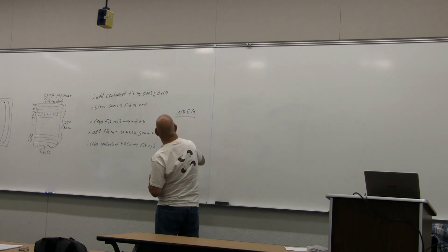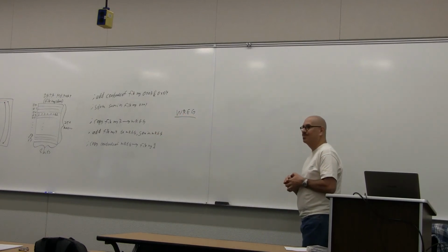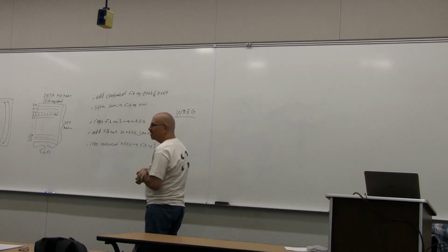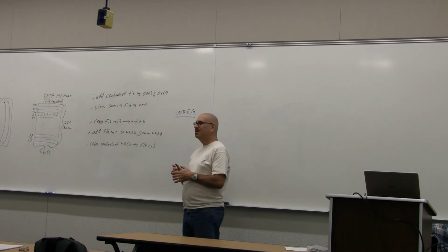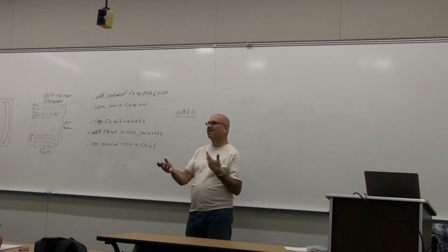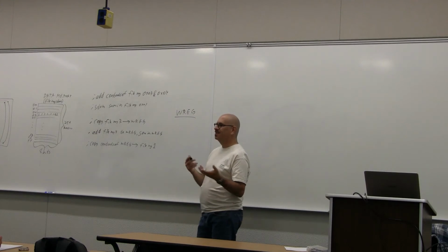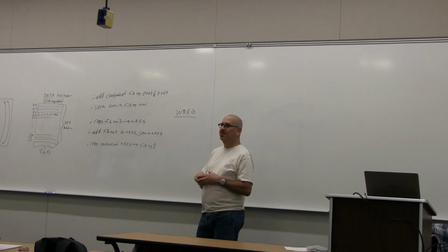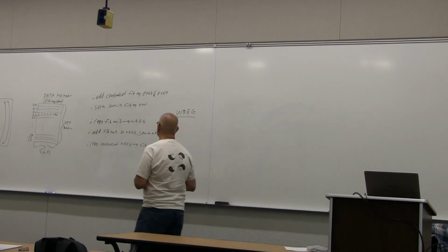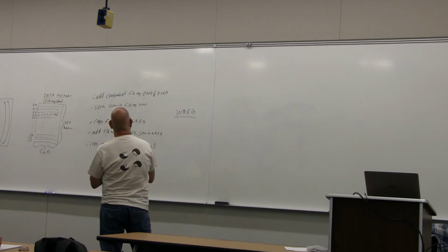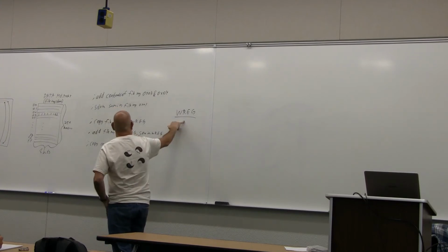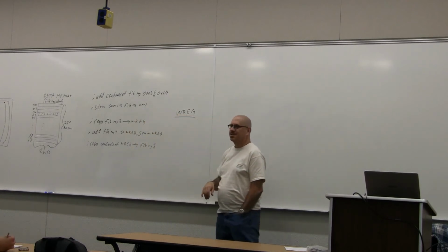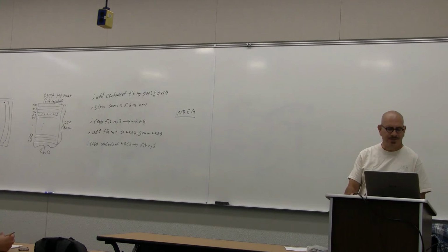All right, so the working register, WREG, is going to be a big part of how we program this chip. We're always going to have to use this. It's going to be a great place for very, very short temporary storage. But it's the only location that we can automatically work with by saying, hey, I want to take this result and store it in the W reg. So we can't use it for long-term storage. But as a little scratch pad area, it's going to be great. All right, so we want to add two numbers together, copy one of them to the working reg, add your second number to the working reg, and then copy the working reg to your destination. But that's how we can add two things together.